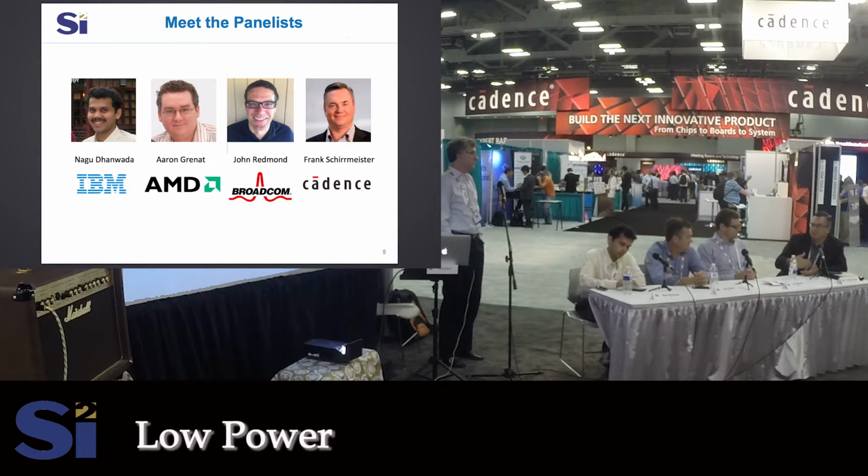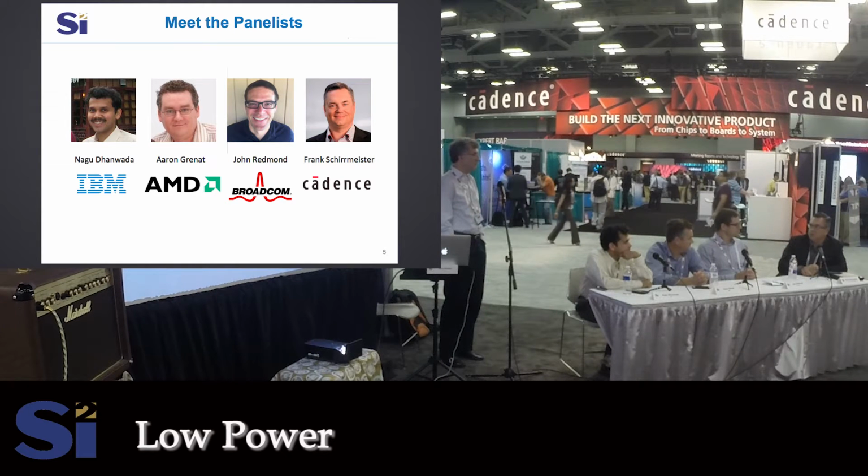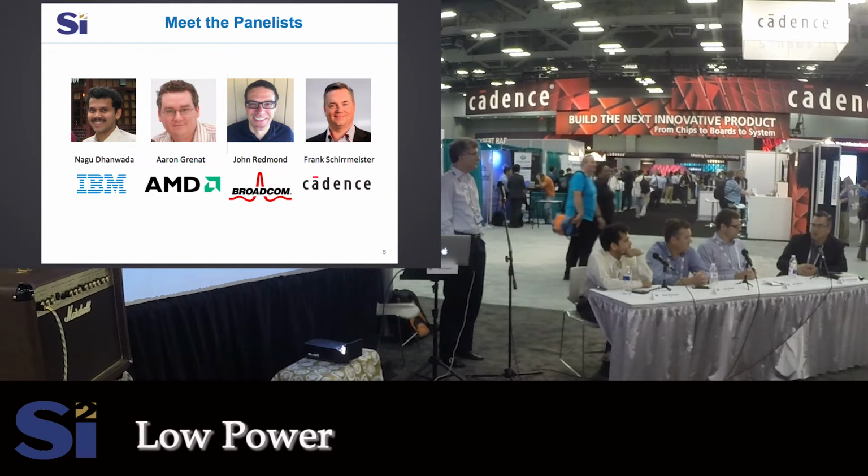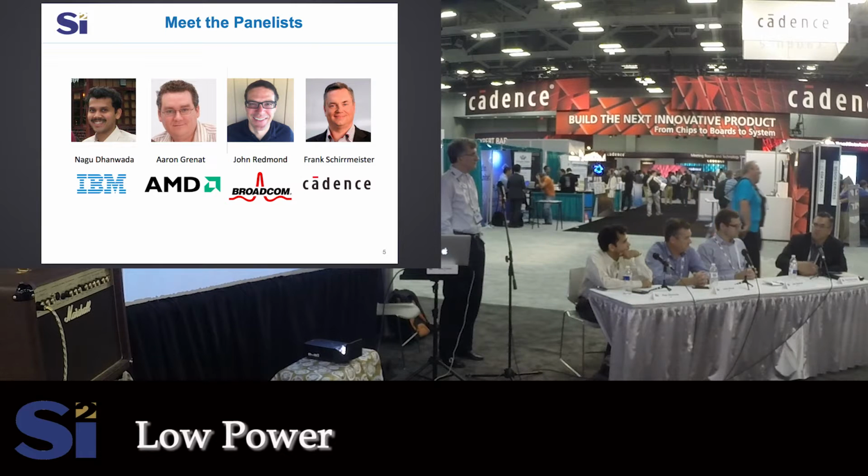Those you can then look into once you have the scenario defined, understanding which of the components are switching on which peripherals, and that gives you a system power view, if you will. And that includes then different perspectives. The software perspective, basically saying, hey, if I move my data somewhere else, I have fewer transactions, and because I keep things more in the cache, that is helpful for power as well.